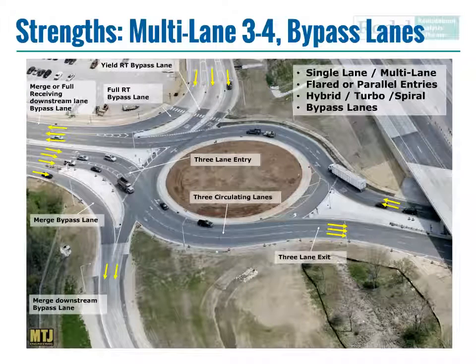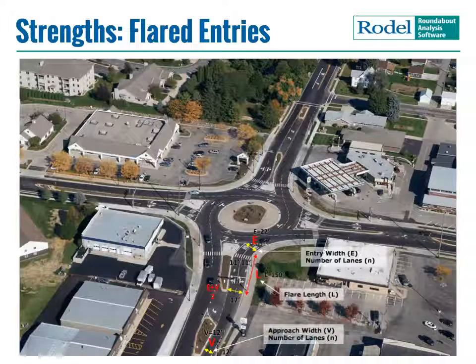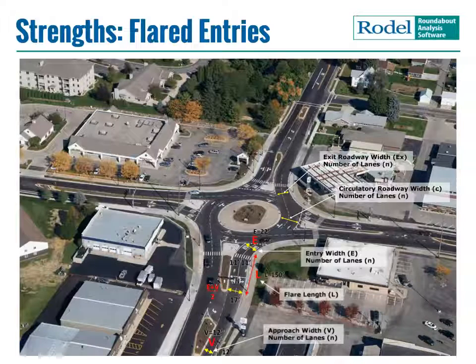This is a 3-lane entry, with a full right turn bypass lane. Rodel can model up to 4 lanes of entry, which is rare, but occasionally occurs. And here's a flared approach. So your approach roadway width V, your entry width E, your distance over which you're flaring. You're going to identify a 2-lane circulating and a 2-lane exit as well. And if you don't identify these correctly, we'll talk about this in a moment, Rodel gives you error messages within its pop-ups, and it doesn't allow you to make the mistakes that were occurring with the previous DOS version occasionally.